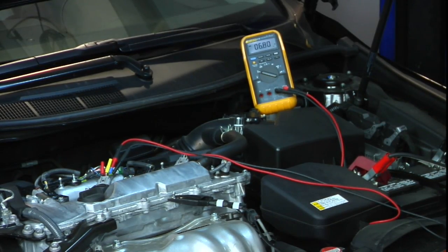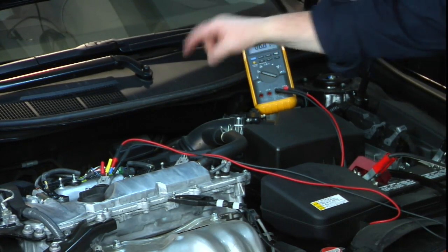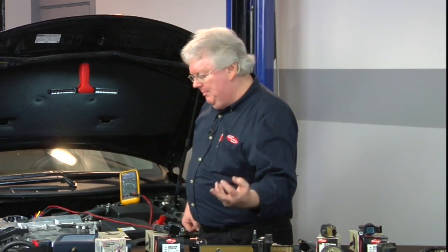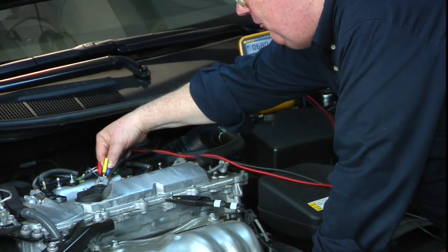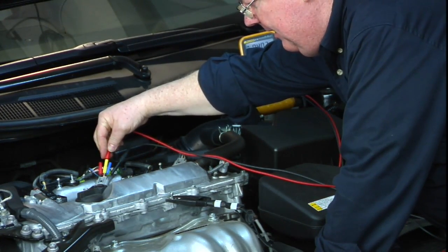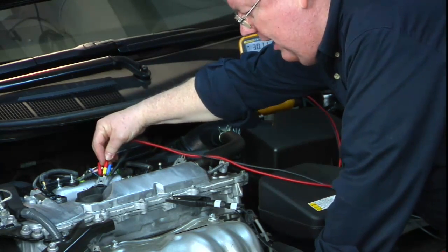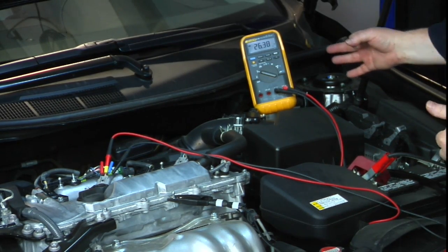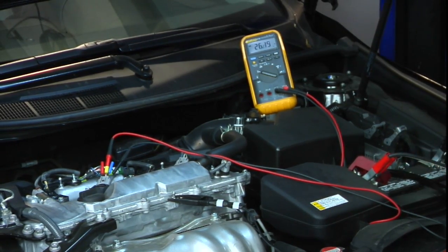And as the engine slowed down, you can see that frequency on my Fluke meter. It's now at 6 hertz, 6 times a second. That's how many times number 2 cylinder is being given the command to turn the primary winding on and back off. And if we want to go ahead and look at frequency over here on the feedback circuit. Now remember, on Toyota, Lexus, some Nissan, that's a unique circuit that is connected in parallel to all cylinders on the engine, and we're going to see some kind of a square wave anytime any of these coils pops, makes spark. So we're seeing about 26 hertz there.